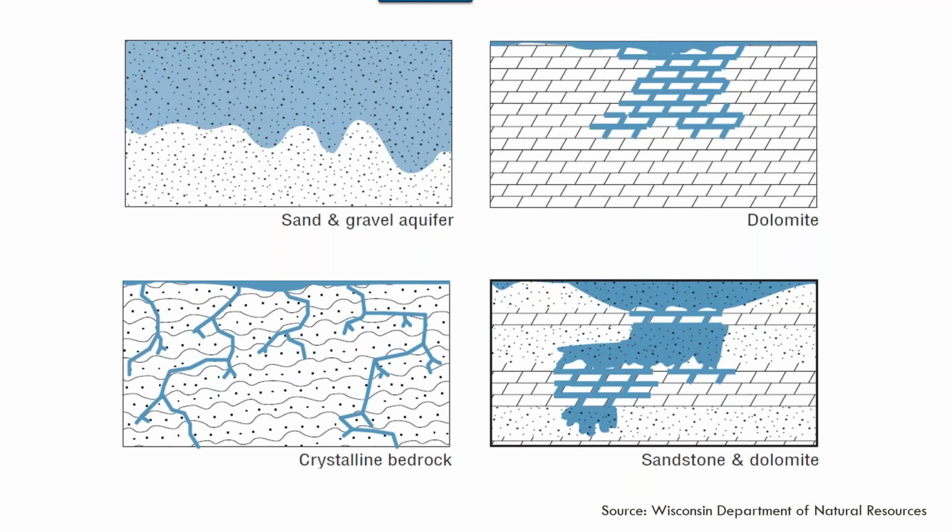As an example, in the Chicago area, the deep sandstone aquifer that's used there for water supply is at between 1,500 and 2,000 feet below land surface. That unit comes to the surface about 50 miles west of Chicago. And so it's at an angle so that the geology drops that same unit, angles down to 2,000 feet in 50 miles. So it's a lot more complicated than what we're showing here is the bottom line.